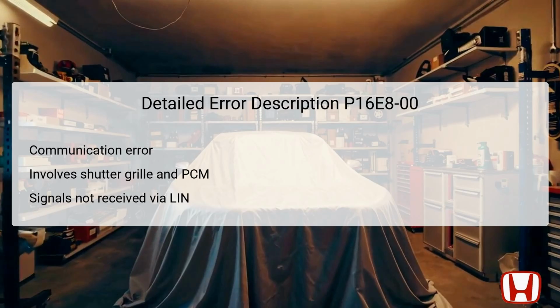When the PCM fails to receive signals from the shutter grille, it recognizes this as an abnormal condition and stores the error code. The shutter grille is responsible for controlling airflow to the engine, impacting both performance and emissions. Its operational integrity is paramount, and if any part of the communication circuit fails, it can trigger this DTC. The position of the PCM, typically under the dashboard, complicates accessibility for visual inspections.